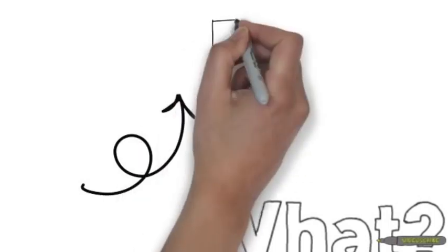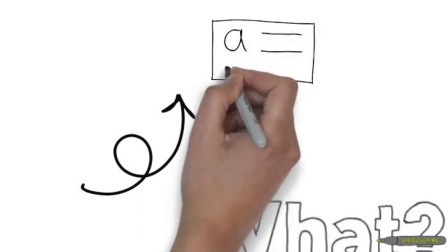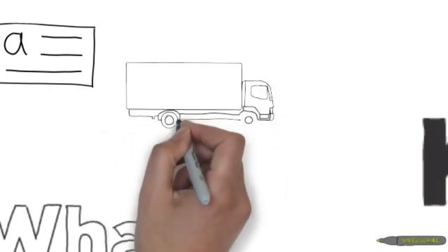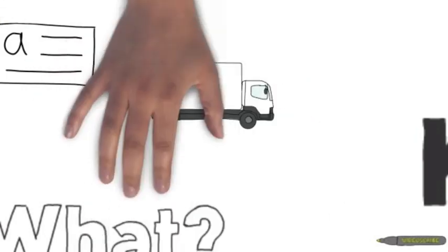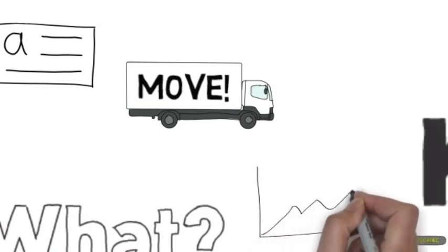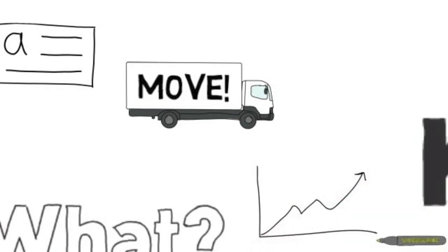Kanban cards are a key component of the Kanban system. They signal the need to move materials within a manufacturing or production facility, or move materials from an outside supplier into the production facility. Consumption drives demand for more production, and demand for more product is signaled by the Kanban card. Kanban cards therefore help to create a demand-driven system.